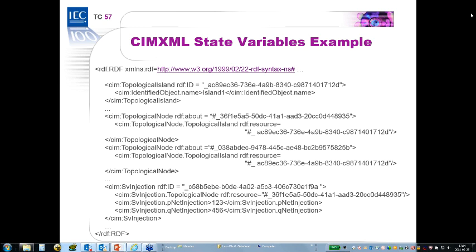And so in terms of supplying the definition of the grid as a whole, each one of the TSOs, A through X over on the left-hand side, is responsible for creating the model part that represents its own territory in the unified grid model. Now, Larzola talked a bit about boundaries. So when you have, let's say, A to B here, you have a boundary between A and B, and there's a formal CIM process for defining the boundary specification. Those boundary specifications allow someone who creates part A to use the AB boundary and the AE boundary to check whether their part fits properly into the whole structure. In other words, you don't actually need all of the other B through X models in order to make that check. You can just do it against the boundary specifications that are relevant to A.